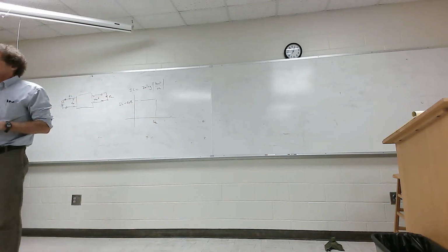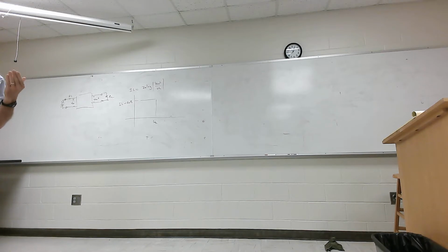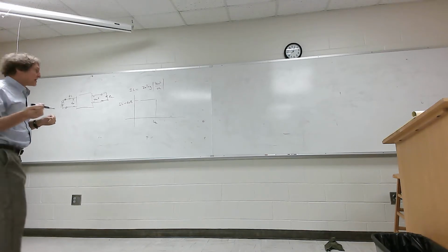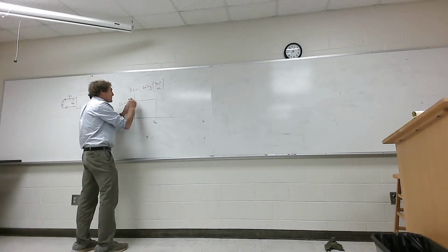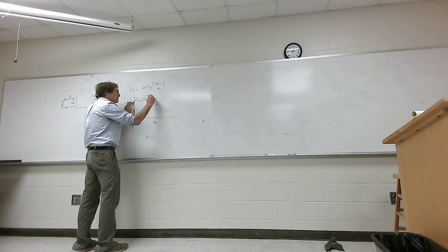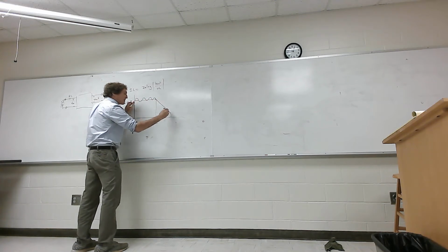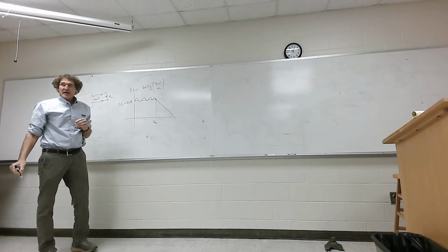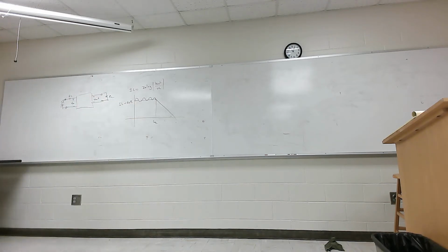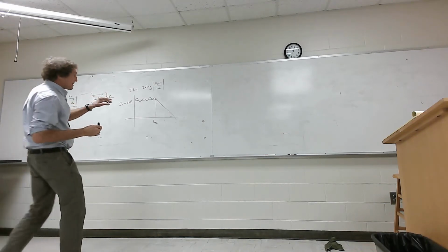It's really the beginning of its 3 dB frequency, where all of a sudden it starts rolling off. With Chebyshev filters, there's going to be some amount of ripple, and then they'll hit here and come down like that. If it's a first order, it's 20 dB per decade. Second order, 40. Third order, it's going to be 60 dB per decade. I'm just trying to make clear some things that aren't in his book, at least in my opinion. So that's what we're really talking about.